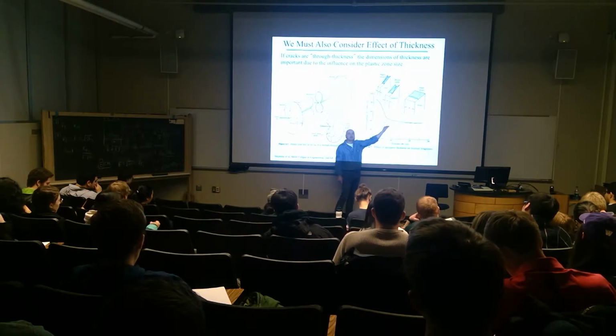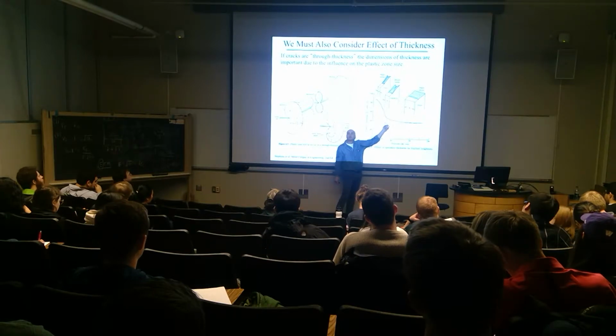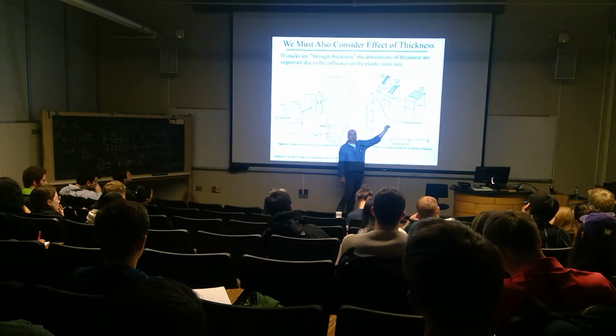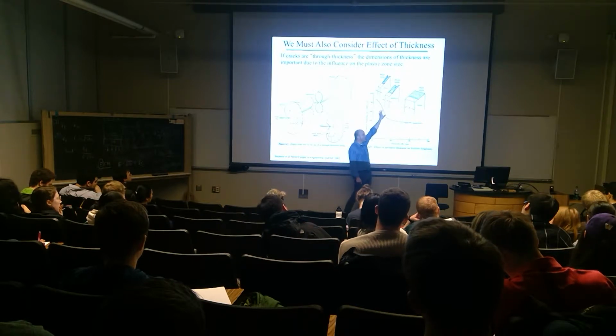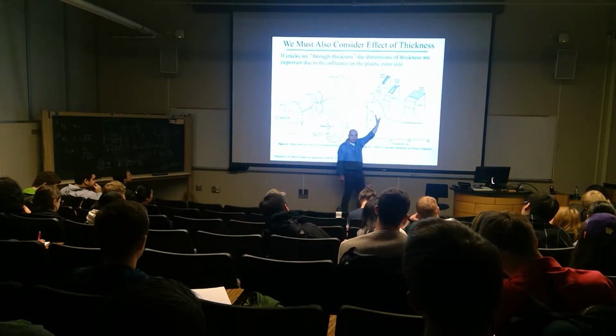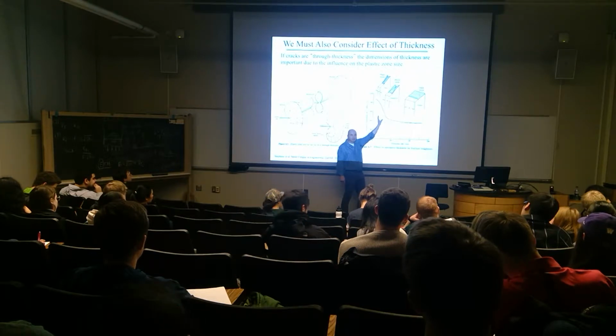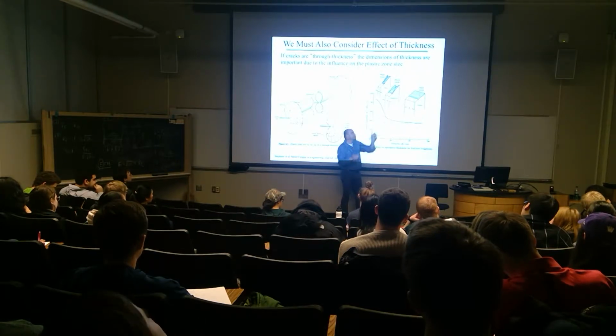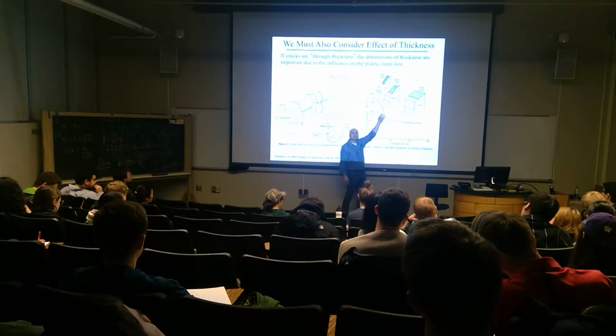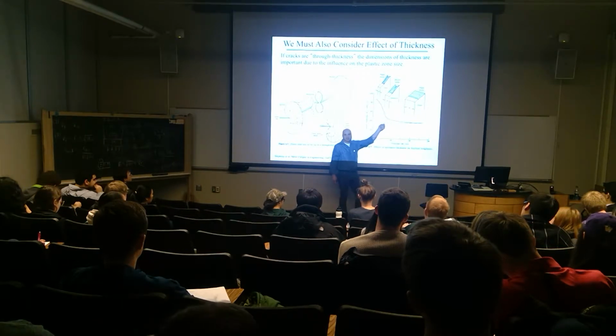When we see reported values for fracture toughness, they're always defined according to ASTM E399, which says we need to always measure the fracture toughness under a plane strain condition, because that will be the lowest resistance to fracture that exists in that structure. So all bodies that have geometry with a larger plastic zone size, smaller in thickness, will be safe. They'll have that added safety; that plasticity will make them safer.